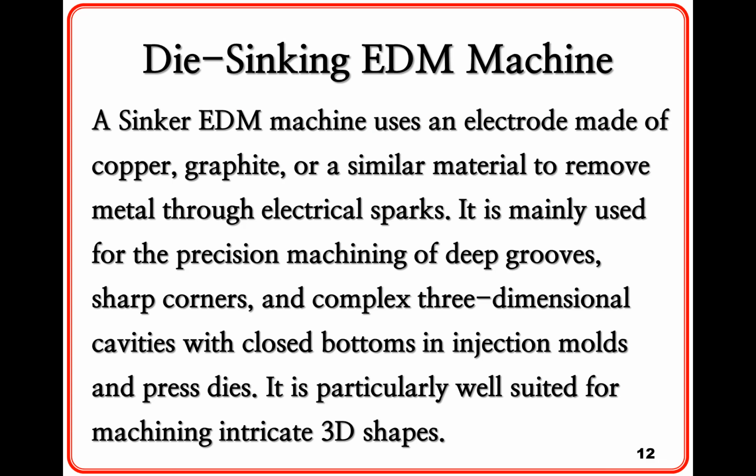Next, let us look at the sinker electrical discharge machine. It is commonly called a sinker EDM or simply an EDM machine. Put simply, this machine can perform machining operations that conventional cutting machines cannot easily accomplish. It is suitable for machining complicated areas that are difficult to reach with ordinary cutting tools. It is also effective for machining extremely hard and difficult to cut materials, such as cemented carbide, which may be very difficult or practically impossible to machine with conventional cutting tools.